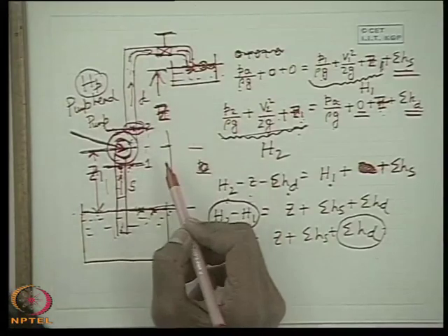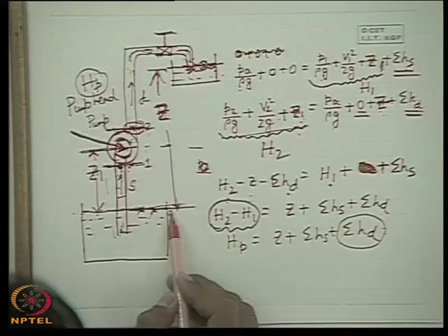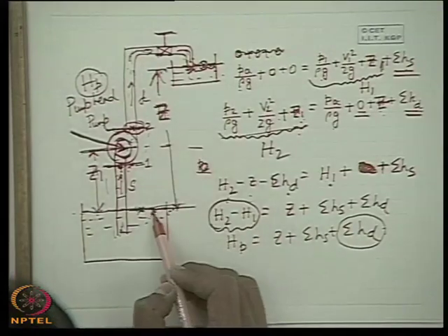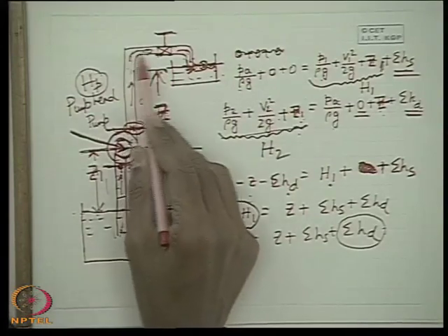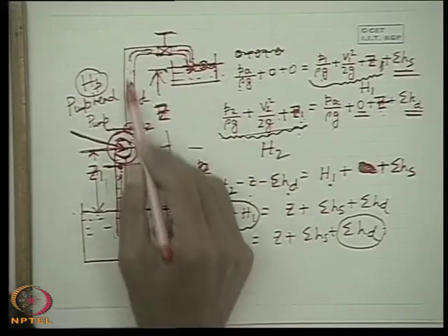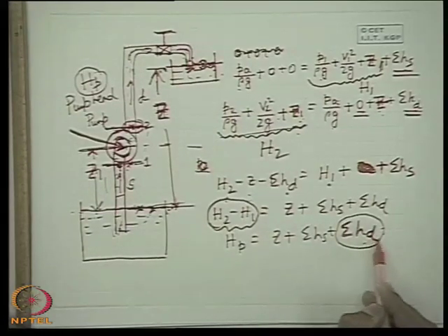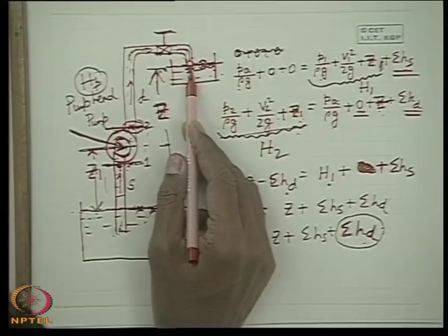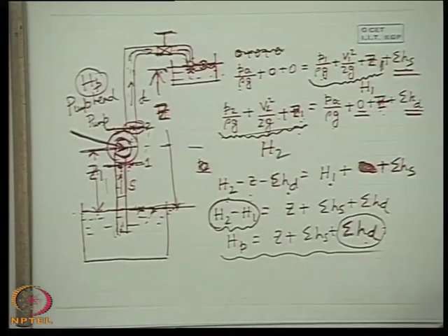So from common energy balance, the pump energy should be sufficient to overcome the frictional loss and to elevate fluid to this height, that is this potential energy, plus the kinetic energy created by the velocity of the fluid, which here is included in the delivery losses as a component, that is exit loss. So from the physics point of view, this is clear.